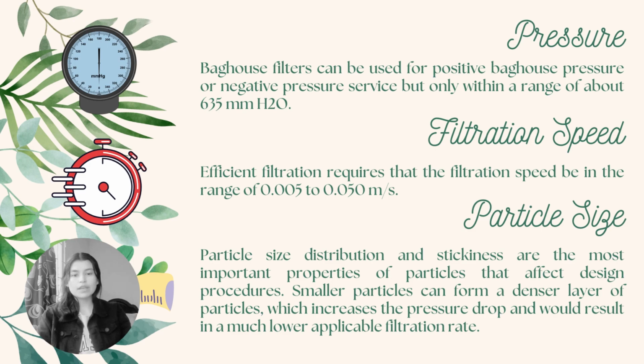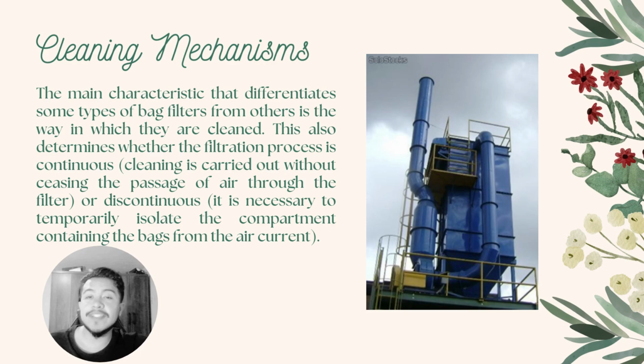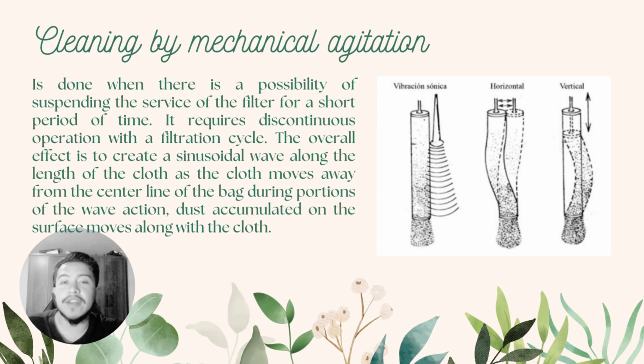About the cleaning mechanisms, the main fact that separates some types of bag filters from the others is the way that they are cleaned. This tells us if the filtration process is continuous or discontinuous. That is, if there are pauses in the filter airflow. The cleaning by mechanical agitation is done when there is a possibility of suspending the filter service for a short period of time. Let's say it has a discontinuous operation.